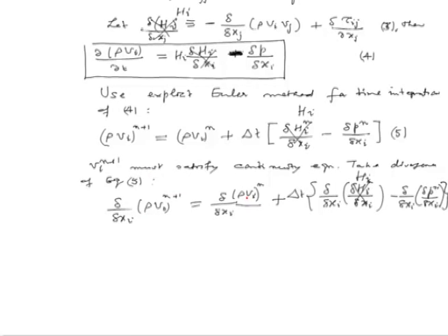Now, remember we have to satisfy the continuity equation. The velocity field must satisfy it at time t_(n+1), so that the first term, the term on LHS must vanish. The velocity field which was available there at time t is equal to t_n, that would also satisfy our continuity equation. So, this term also vanishes. So, these two terms vanish for continuity.